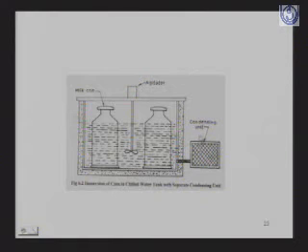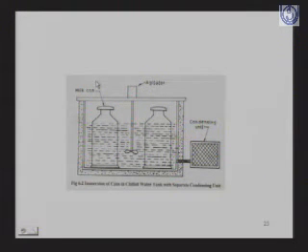Otherwise, continuing, this is a type of condensing unit, that is, we attach a refrigeration unit to this. The water is continuously chilled, and with the agitator we are moving the water so that the temperature doesn't rise high, and we can chill the milk. Here the cost will be more, but the advantage is that you will be able to increase the shelf life of the milk. In the first one we cannot extend the shelf life to very high.